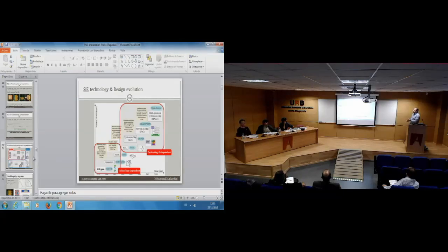If the transistors are still in photolithography, the mask is already prepared. So why not also use the pre-patterned wire cells in photolithography as well, and just leave the customization to inkjet printing? Because if we want to have both pre-patterned wire cells and the final customization by inkjet, we will reduce the density dramatically.